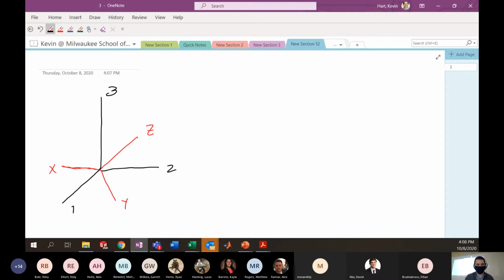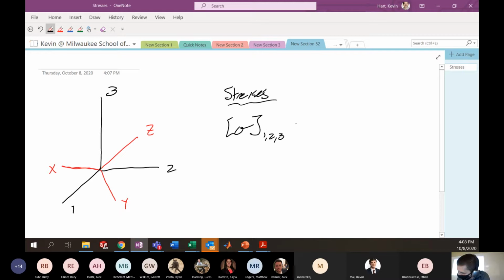All right. So one way that you might do that is transforming stresses. You might have the stress in the 1, 2, 3 coordinate system equal to this transformation matrix that we showed before. I'm not going to write the whole thing. It's a 6 by 6 matrix multiplied by stress that exists in X, Y, Z. You could also imagine the inverse of that, or if you want the stress in the XYZ coordinate system, you multiply T inverse by sigma 1, 2, 3. Well, that's pretty straightforward. We also looked at strain.